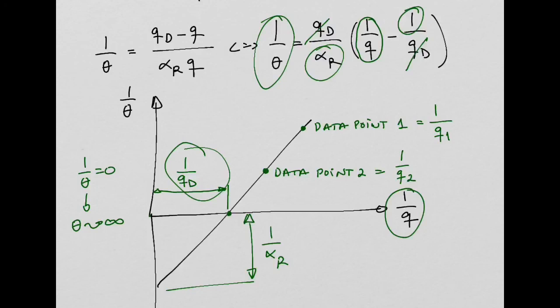All right. Any questions? Static divergence. So it's a very important thing in the design of your wing, right? We should not allow the wing to reach that point. So we need to try to design our wing so that the divergent velocity is as high as possible. It means you can fly faster without the divergence occurring.